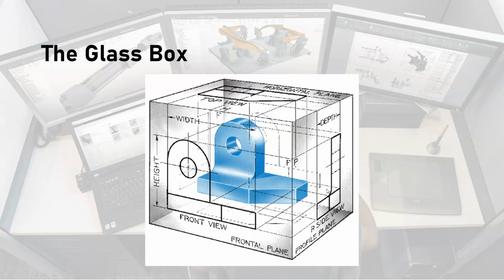So when we put 6 of those projection planes together and we surround the object, that's when we have our glass box, okay? And if we use the same idea of projectors and projection plane and tracing the surface out, what we end up with is a front view that's traced on the front projection plane, a right side view where the projectors come across here. You can see some of the projectors, and they trace out a right side view on the right projection plane.